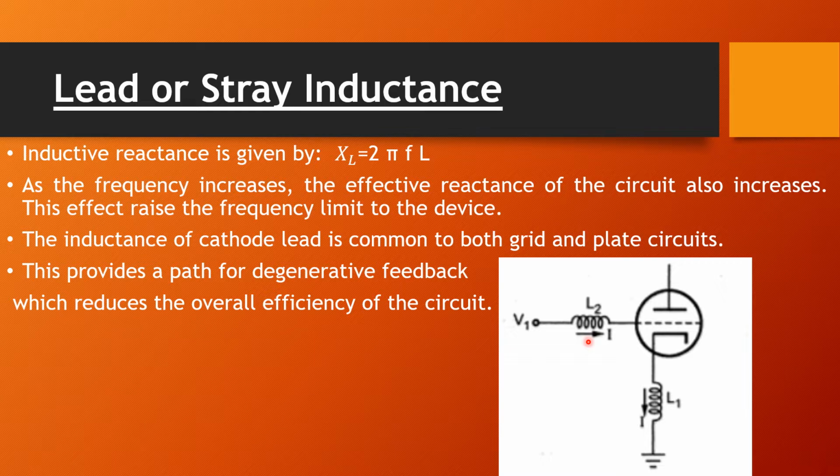At microwave or high frequency, this inductive reactance is very high. So with conventional devices, due to the lead inductance, the electrodes appear as an open circuit to the input as well as an open circuit to the ground. So whatever current or voltage is coming from here will be dropped midway and will not reach the actual device.